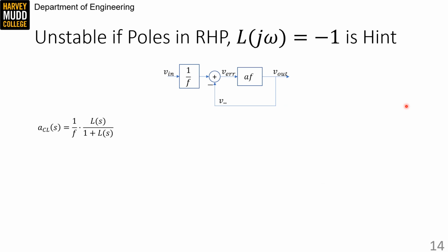Alright. So now that we have a sense of what instability is, we're going to start developing a stability criteria for our transfer function. We're going to start by considering the feedback system pictured in the center of this slide. And we notice that it has the closed loop transfer function I've indicated on the left. The first thing to note is that this closed loop gain is a transfer function, so if any of the roots of 1 plus L of S are on the right half plane, it will probably be unstable. It will fly off to the rails and start doing something nonlinear.